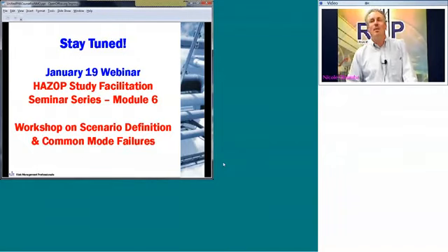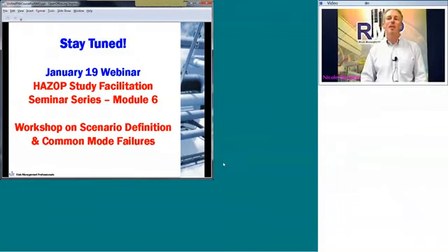If it's always open at the same %, I think you need to stroke it a little bit to see if it's going to function. So I wouldn't consider it necessarily a monitored component. However, it is something that's a little bit better than no flow, but not all the way to validating its function. And in fact, that's another good question for another reason too.